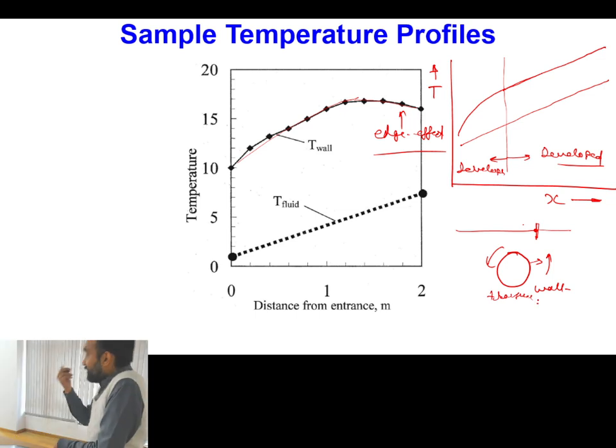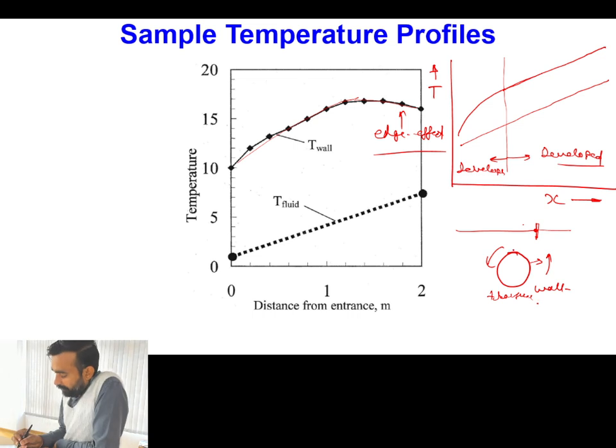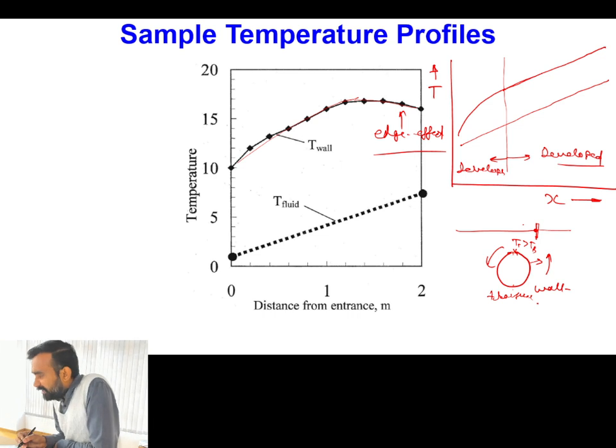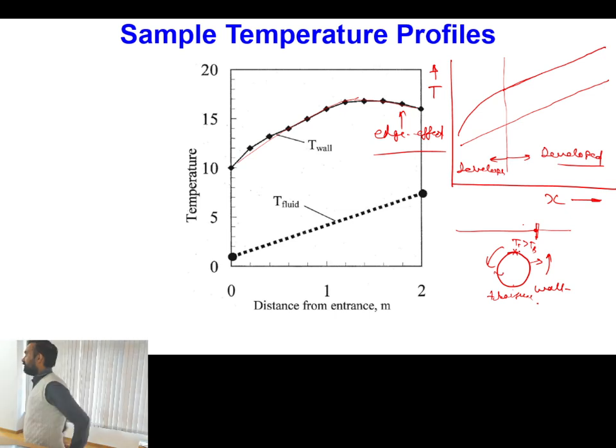But in actual physical systems, whenever you will be working, you may find that temperature on the top location is slightly higher in comparison to the temperature on the bottom location. So in this scenario, if there is a temperature difference of 1 degree or 2 degrees along the wall of the tube, in the transverse direction there will be some conduction heat transfer.